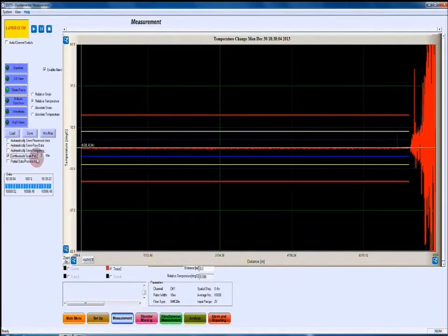And on here you set a time frame over which to make those scans. So right now we have it set up to continuously scan every 3 minutes. So right now, every 3 minutes, the computer will take a new scan off the fiber. So depending on how often you want to take a reading, you can increase or decrease the number of minutes between scans.